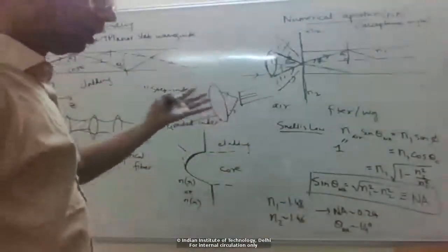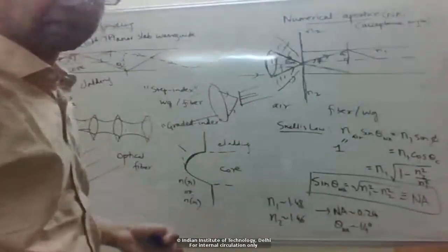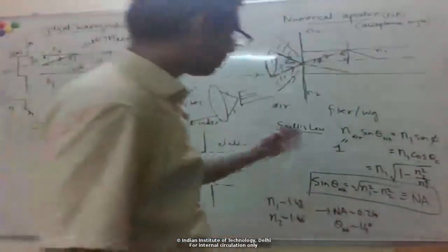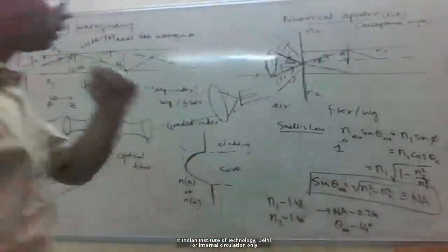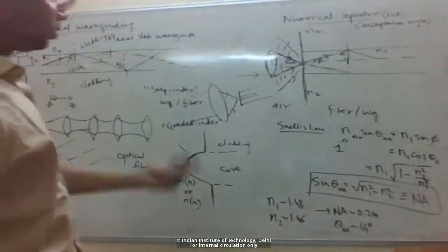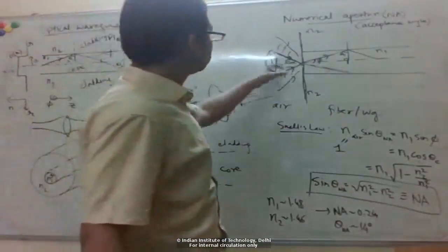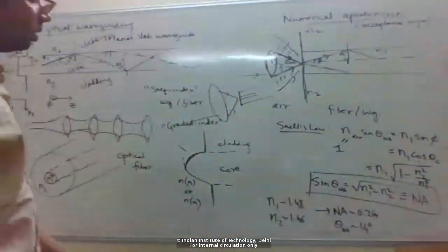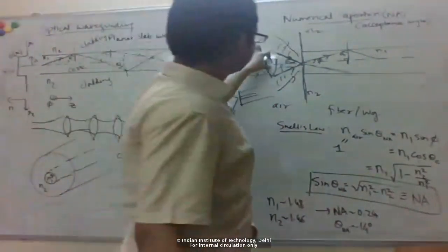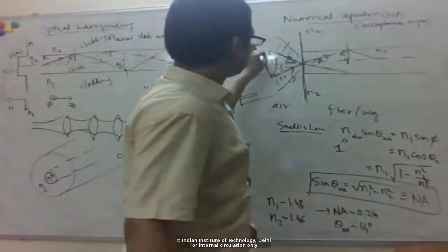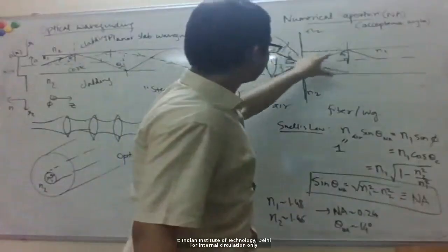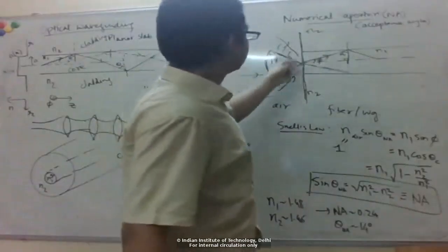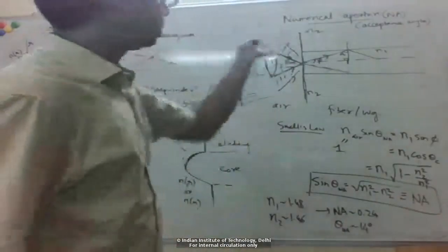Nowadays, we mostly use single mode fibers or few mode fibers, which will have an even smaller NA. Okay, so they'll have like 0.1 or something. So now, if you want to couple efficiently from free space, you want to use a lens which has an even smaller NA than that, right? Because only the rays which are within the cone of the acceptance angle of the NA of the fiber will get coupled, right? The rest of the rays will get lost.